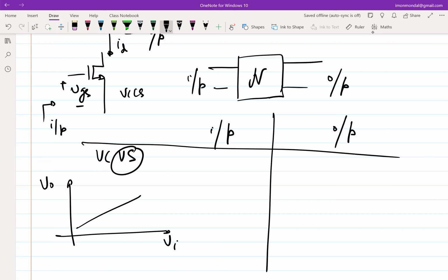Yes, correct. So what he's saying is that it depends on whether the black box acts as a source to whatever has been connected to the output, and what type of source. So that's essentially the question. If it's supposed to be a voltage source, what characteristics of this box do you need to check to figure out whether it's a voltage source or not? Output impedance, right? The output impedance has to be very small compared to whatever you are driving. Ideally, for a voltage source your output impedance has to be 0. This is ideally, so this is ROC.